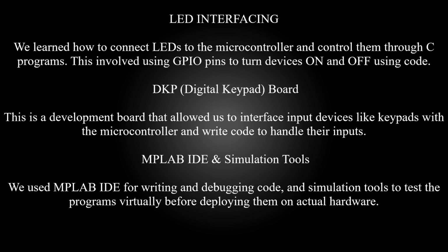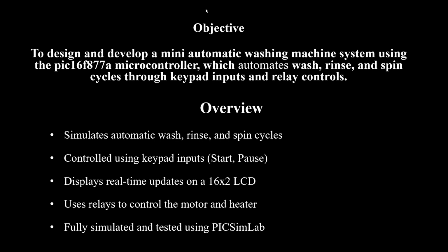DKP, digital keypad board: this is a development board that allowed us to interface input devices like keypads with the microcontroller and write code to handle their inputs. MPLAB IDE and simulation tools: we used MPLAB IDE for writing and debugging code and simulation tools to test the programs virtually before deploying them on actual hardware. And we developed a mini automatic washing machine system using the PIC16F877A microcontroller, which automates wash, rinse, and spin cycles through keypad input and relay controls.